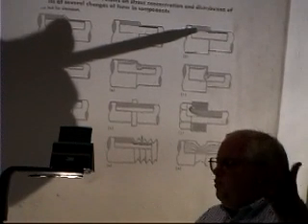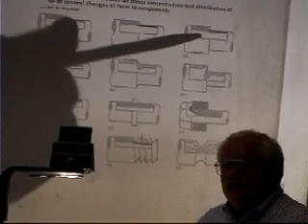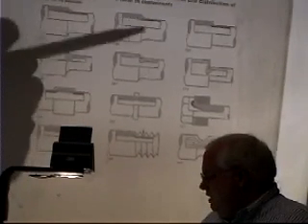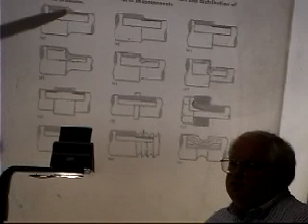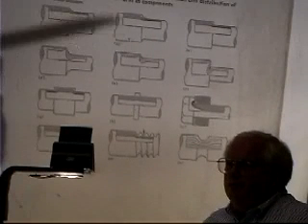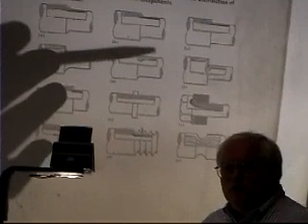That could well put me into the range where I get fatigue cracking. And so that's why you get cracks in keyways and things like that. If you have a gentle thing like this, your stress concentration may be 1.4. You get a 40% increase in stress. No big deal. Within the error of the analysis in most cases. So you don't want sharp changes, you want gentle changes.